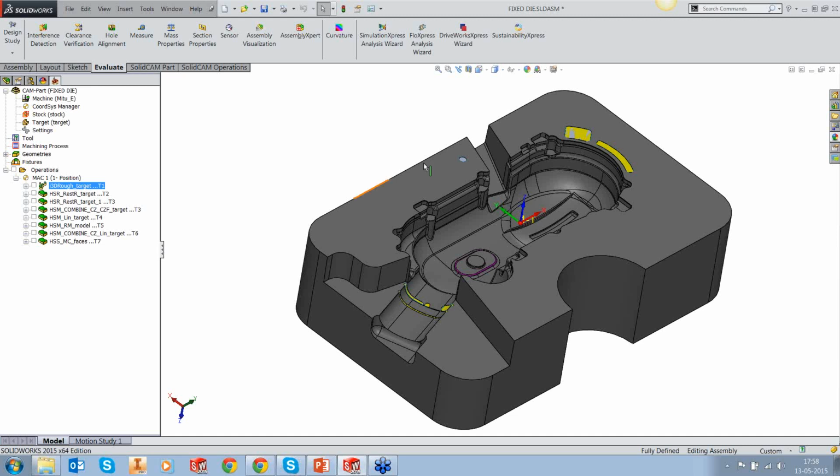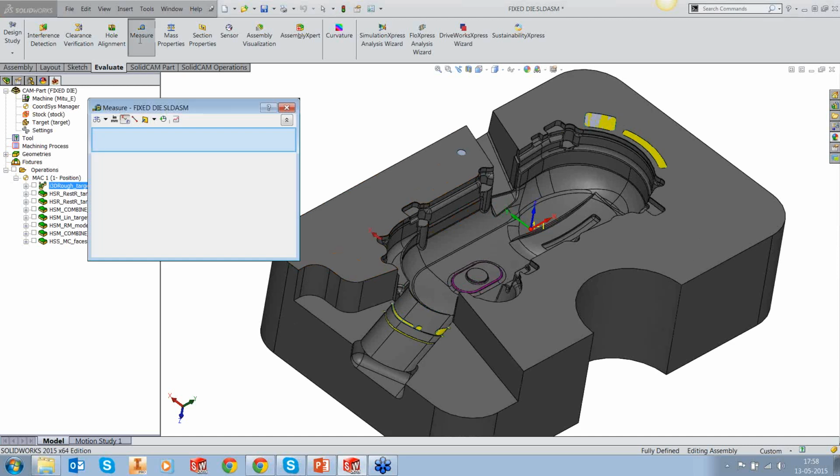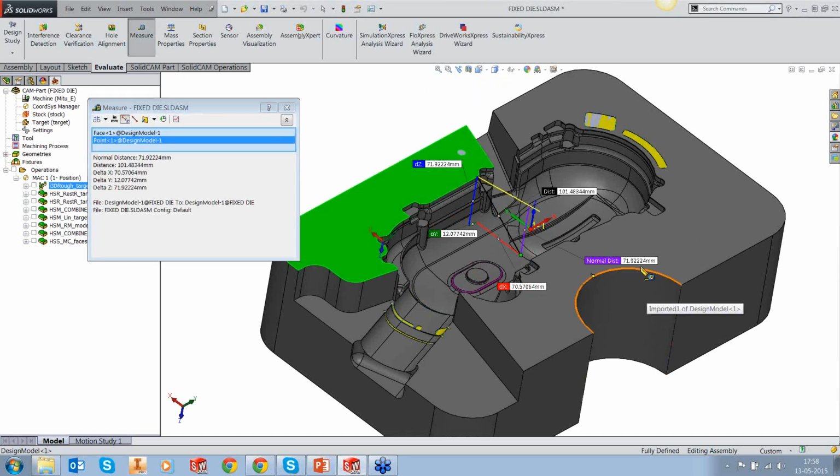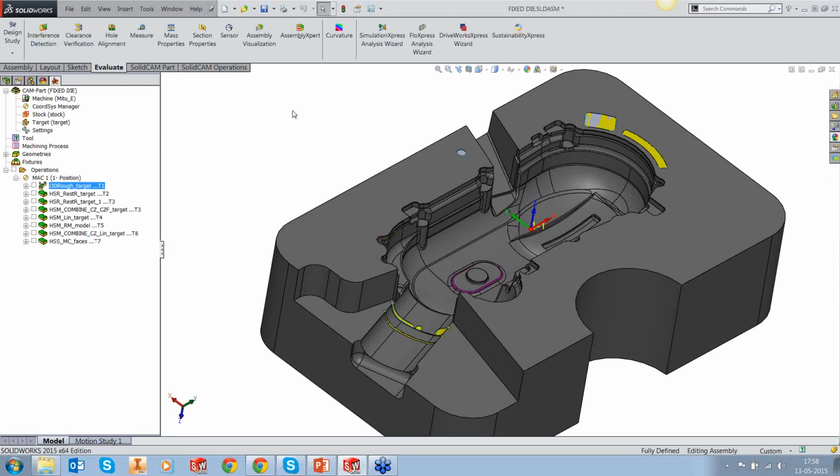First of all, it's very important to understand what is the height that we are talking about roughly. We are talking about 71 millimeters out here. So the maximum possible end mill that we would get for iMachining, which is economically viable, is about 16 millimeters. If I use 16 millimeters, the best possible cutting is at an L by D ratio of between 3 and 4.